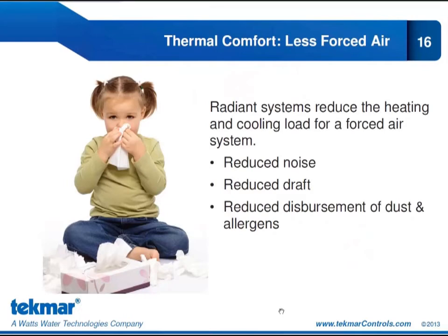Another point that speaks to the enhanced thermal comfort that a radiant system provides is that there is less forced air. What I mean by that is the forced air system is used less often because that base load of heating or cooling is being addressed by the radiant system. One of the most common complaints that we hear from owners of forced air heating or cooling systems is the amount of dust and airborne pollutants that are distributed through the building, through the ventilation system. So we can reduce that by becoming less reliant on a forced air system